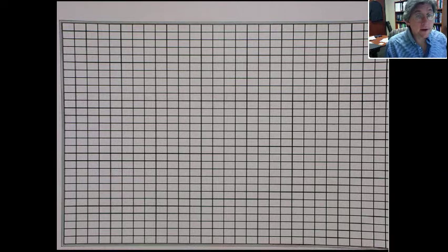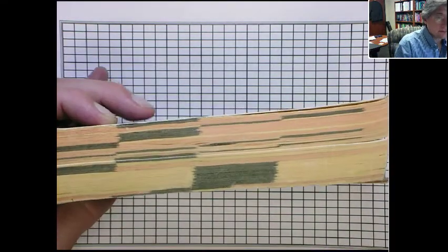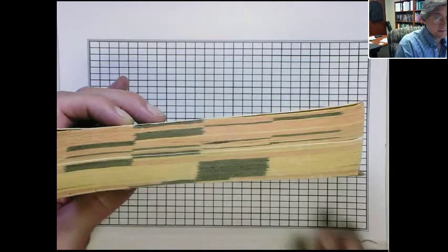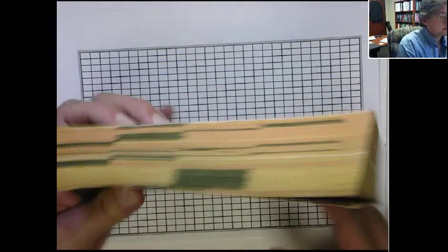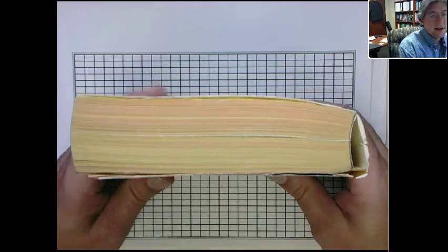So in this video, we want to talk about not how the normal stress and the normal strains are related, but how the shear stresses and the shear strains are related. Okay? And it turns out they're analogous. It's a linear elastic relationship between shear stress and shear strain.